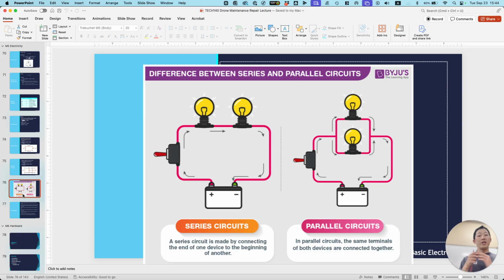Yeah, so with voltage, you measure in parallel. With current, you have to measure in series. You have to break the circuit. You have to be one with the circuit, I guess, is what I mean by that.